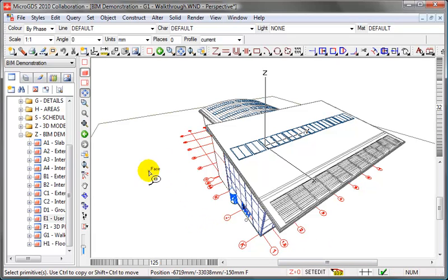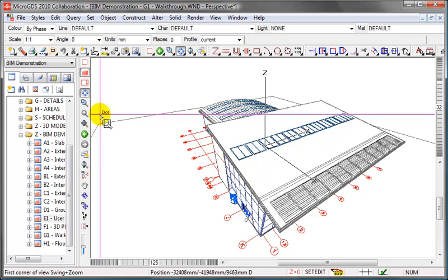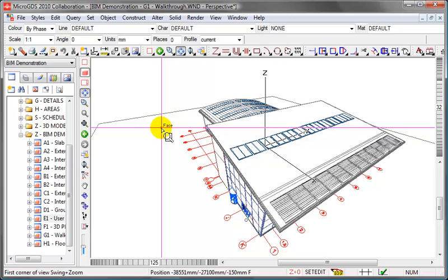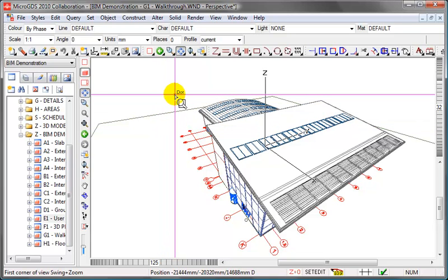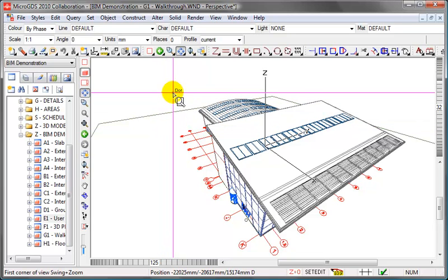You can also use the zoom rectangle command. You'll have used this a lot in your 2D views, but it also works in 3D. But instead of defining a rectangle, it defines a 3D shape, something that's called the frustum, which can be extremely frustrating to use, which is actually a pyramidal volume that describes the 3D extent that you're actually trying to view.